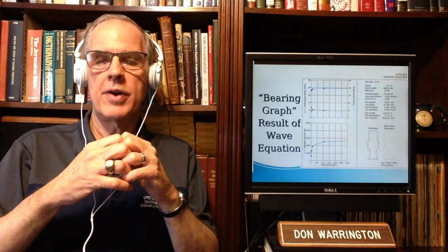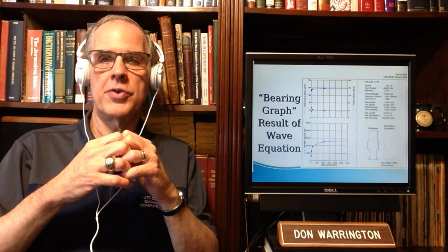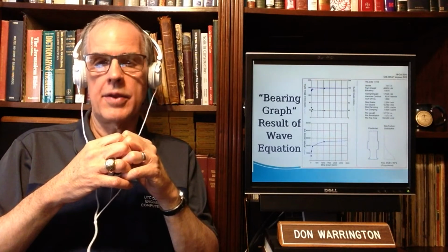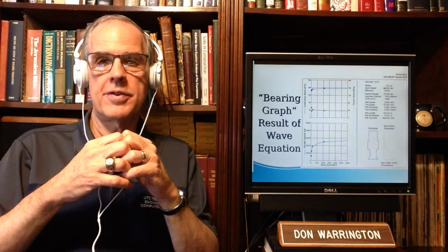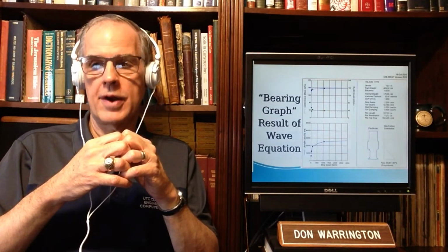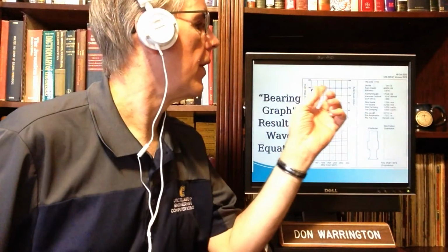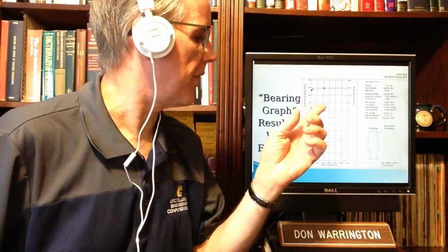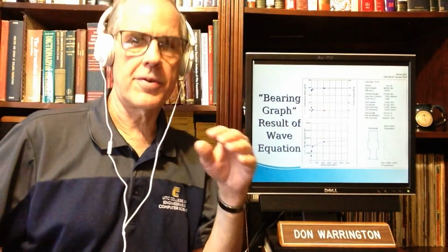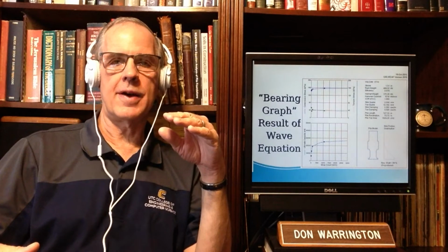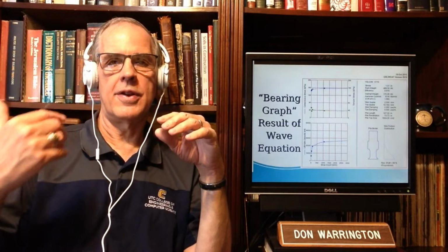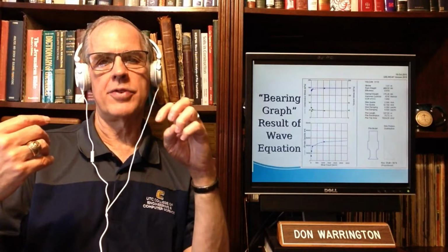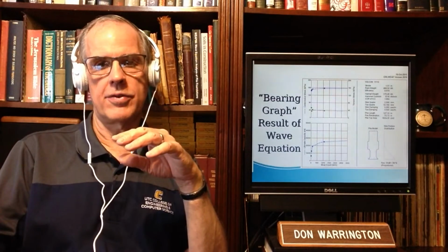The second thing is compressive stress. Obviously, we don't want to overstress the pile in compression. And the wave equation is capable of estimating the maximum compressive stress in the pile during driving, and that is up here. For this particular case, this is an offshore type of pile, and like I said, with offshore piles, the top and the bottom tend to be decoupled, so the compressive stresses are not as influenced by the blow count. In many piles, the higher the blow count, the higher the compressive stresses.